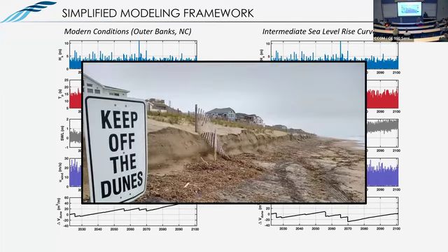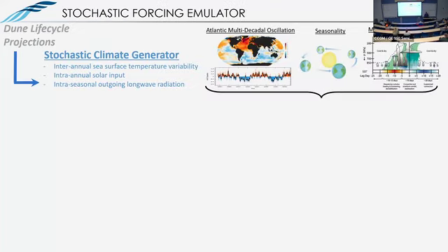And that's a problem with deterministic models: we have one answer and it's dependent highly in terms of what we say the winds and the waves are going to look like in 2048 at 12 o'clock. And we have no idea what they're going to look like, right? So oftentimes just taking a forecast isn't that useful in getting one answer out. So we've been thinking a lot about, with these tools that we're developing, how can we put this in probabilistic space? Because this is really important for how we design this dune. And it's really important for those houses behind the beach in terms of whether they're protected or not, because if we get this wrong, they're pretty easily going to be gone.